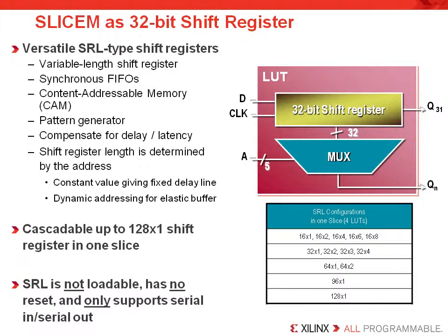The most challenging thing with this is that most customers don't realize that it is not loadable, has no reset functionality, and only offers serial in, serial out capability. So if you try to infer it with any of these behaviors, your synthesis tool will instead infer regular flip-flops. And of course that will be a big waste if you're building a large component and expecting the shift register LUT to be used. The benefit of this resource is that it can effectively provide the work of 32 registers with a single lookup table. And in pipelined applications, that is a huge savings.